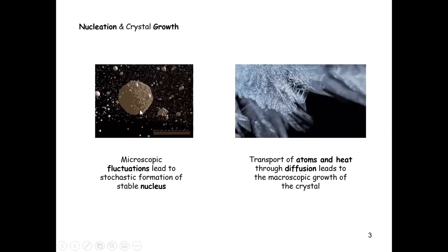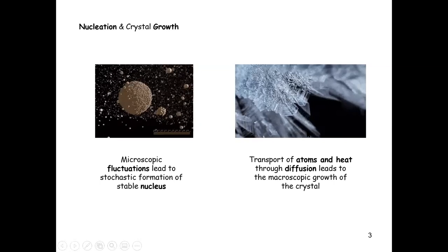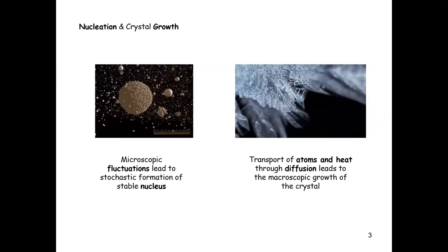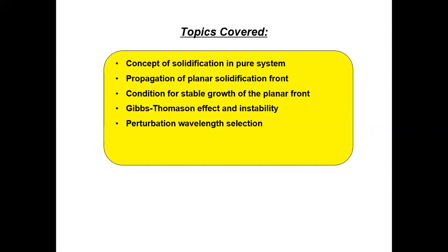the small solid nucleus form, we have to worry about the growth, right? How you add more atoms to the small nucleus. So this is the key process we're going to focus on for this class. In particular, we talk about the concept of solidification, in particular, the growth of the nucleus in pure system. And in this context, we can analyze the propagation of the planar solidification front.